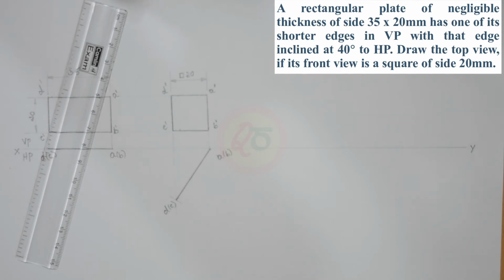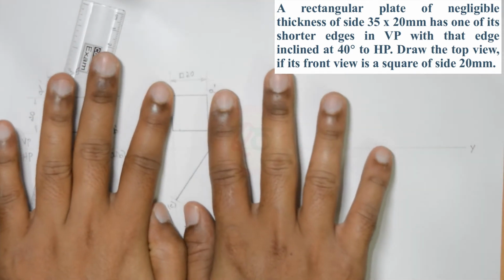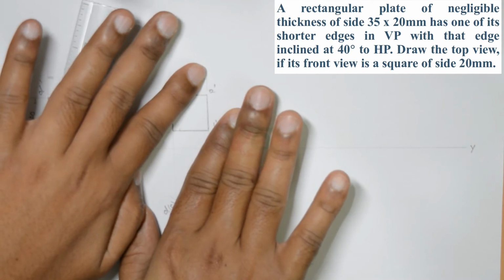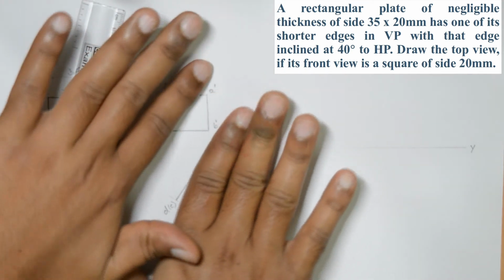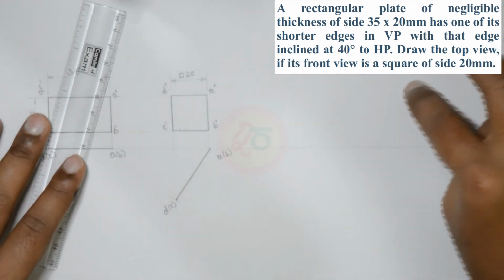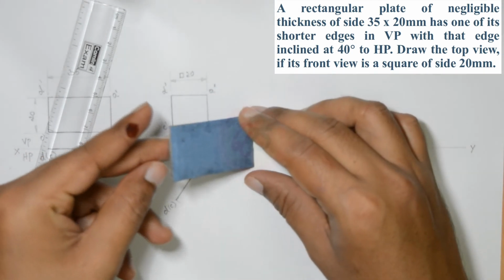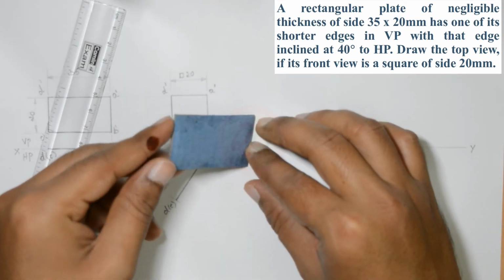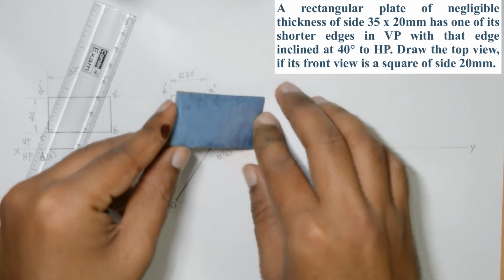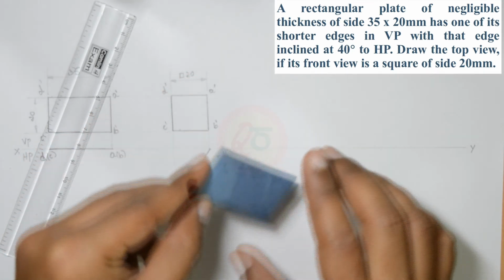So in the VP plane, this square will rotate clockwise in such a way that A dash B dash will be inclined at 40 degrees to HP. So this square looking rectangle, the edge which is on VP will make an inclination of 40 degrees to HP. Okay.